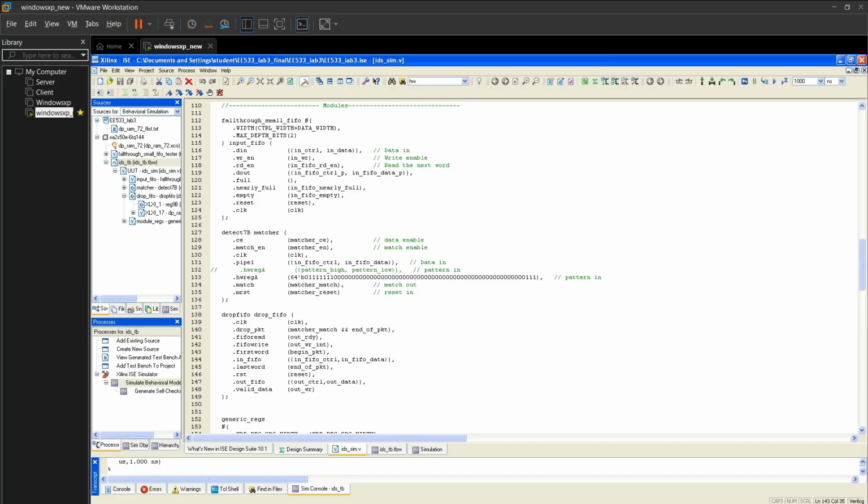I'd also like to point out this. Reg 7A is the register we are going to check for a match. So we're checking whether there's any match with this pattern for the whole set, a 7-byte set. And as you can see here, this is our A mask. What this means is that we're checking for all bytes in the 7-byte array. Here everything is one, which means we're checking every byte.